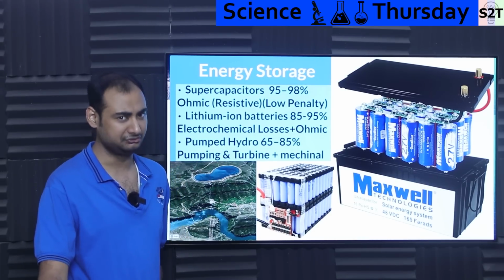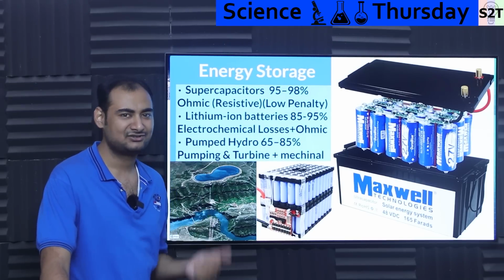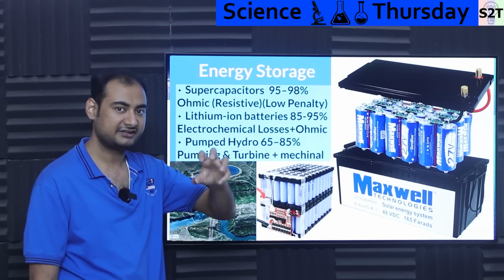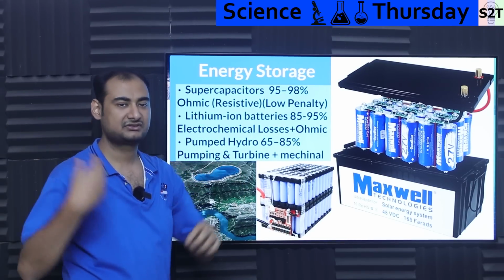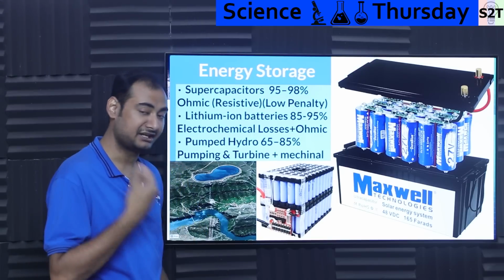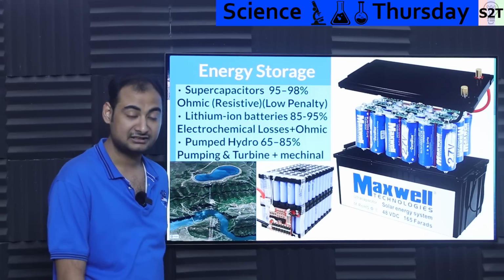85% is like a really, really fine-tuned system. Now, why is that? Well, pumps are not 100% efficient, even compared to the mechanical motion on the shaft itself versus how much liquid is traveling up. And turbine, again, the same thing. A turbine will waste some amount of energy. So those things are there, and then you have mechanical frictions and all that.